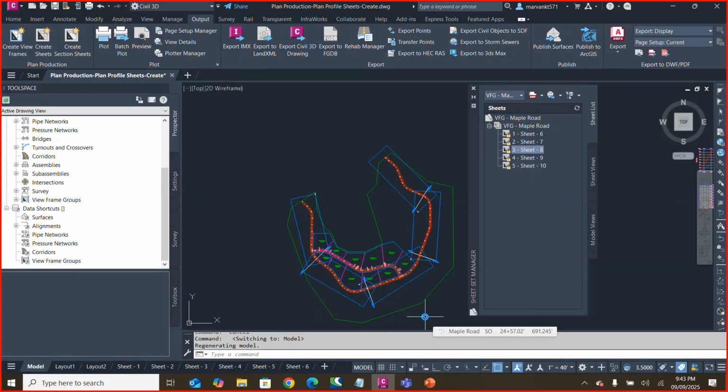So normally the difference between the consultant drawing and the contractor drawing: when it comes to the contractor drawing, more details in terms of model and in terms of information should be provided. Normally the consultant will practice on LOD 300, the contractor's drawing will be LOD 400, and the as-built drawing will be LOD 500.